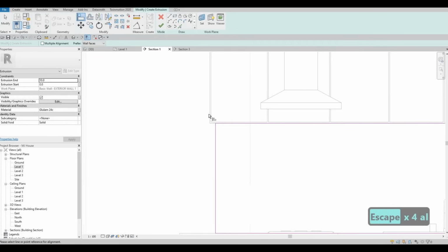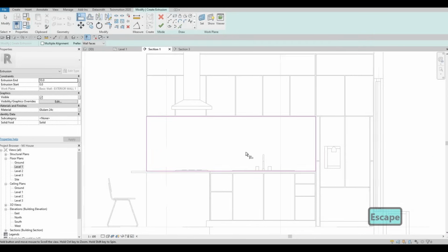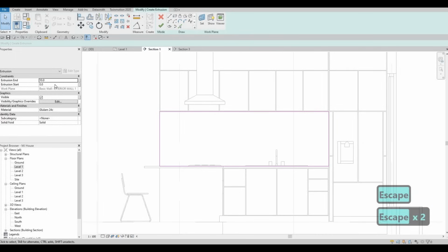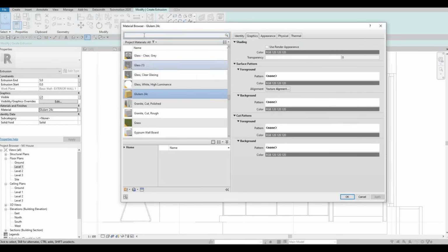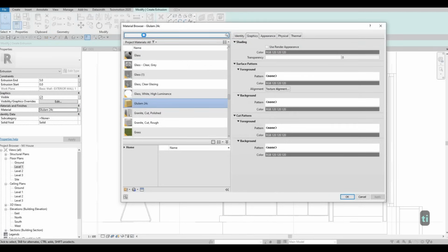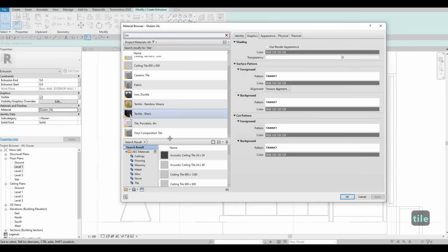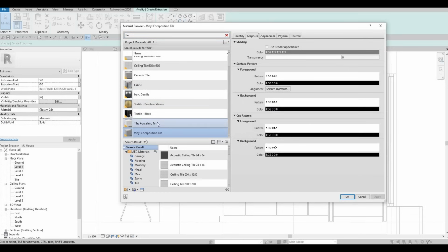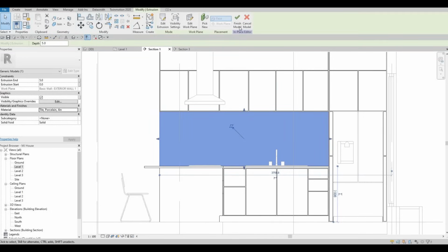So you're basically telling Revit you're gonna place it on this plane, and then you're gonna attach it from there. So here I'm going to put it at 5, and then going to add something that is styled. I'm just gonna choose this style and then click on finish.